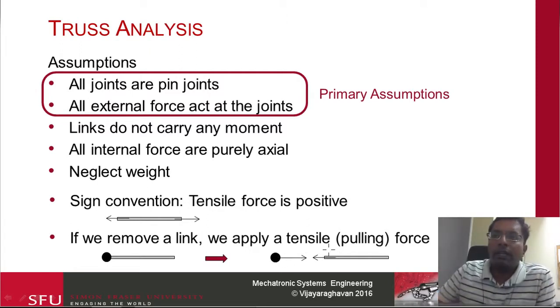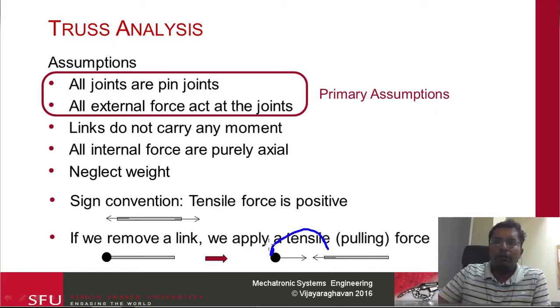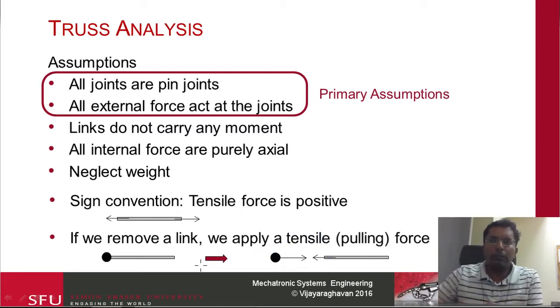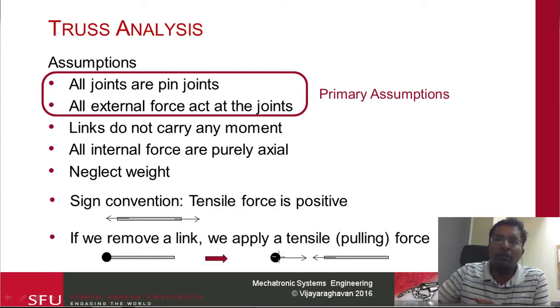So notice that if I bring this over here, these two are what is known as internal forces. So this force would be equal to this force. They'll basically cancel each other out. There wouldn't be any force when I assemble it together, so there is not a net external force. So this is important. Make sure that the forces are equal and opposite. Because you're assuming tension, this needs to be a pulling force, so basically in this direction, and then that results in a pulling force on the link as well.